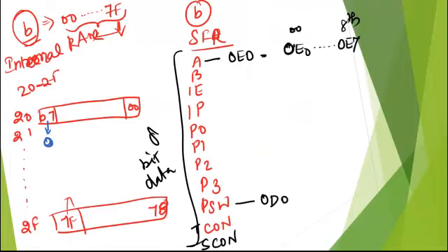And as I said, from 20 to 2F you have the bit addressable memory location, from 00 to 07 and till 20 to 2F, the last memory location is 7F. So each bit is given an address and each bit we can access. Okay, this is said to be bit addressable memory location.